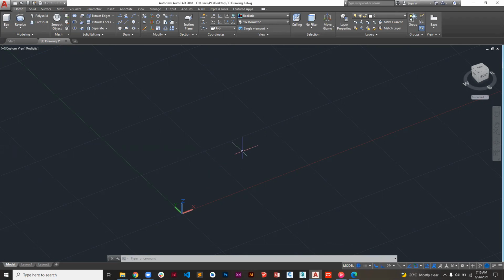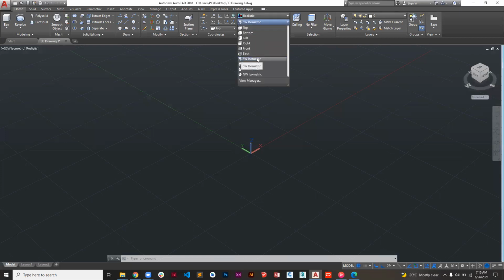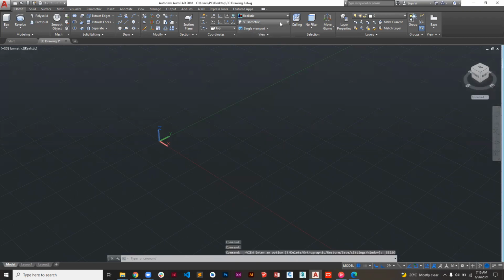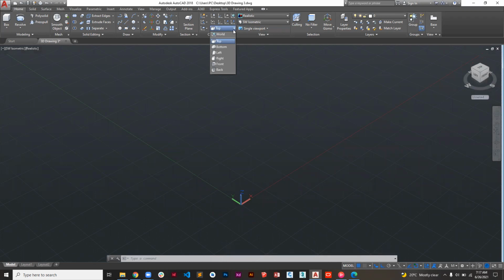So now that means we need the object, then we also need a line that's going to revolve around. So I'm going to start by drawing a line. Just ensure that you are in 3D, or you can just come here and change the view to either southwest or southeast. But I'm going to work with southwest. Then here, these ones, I used them last time, but I think I didn't deeply tell you about them. This one just helps you to switch the grid.